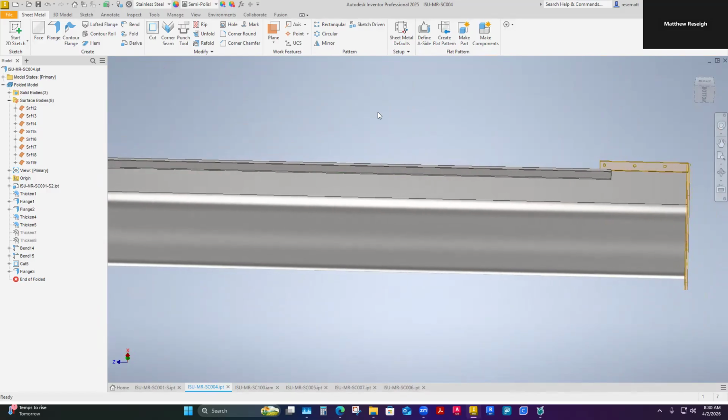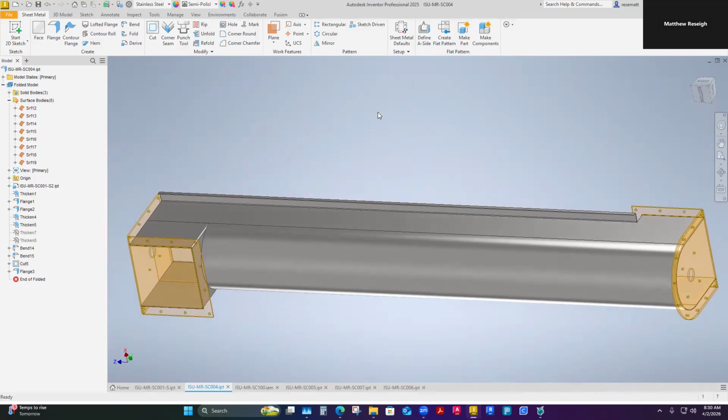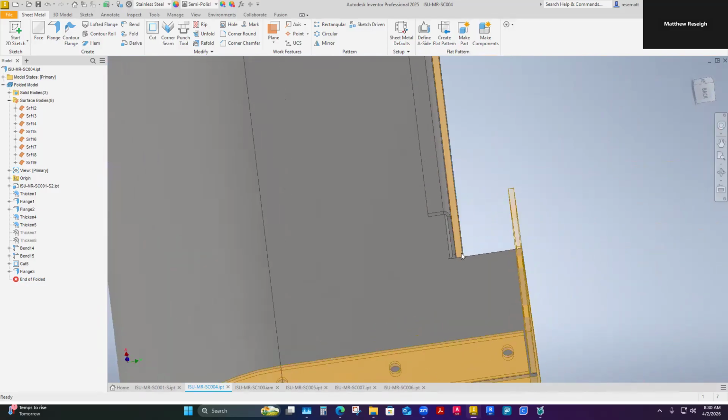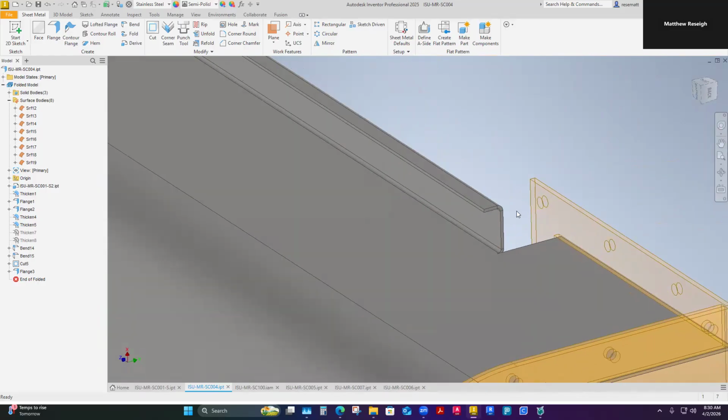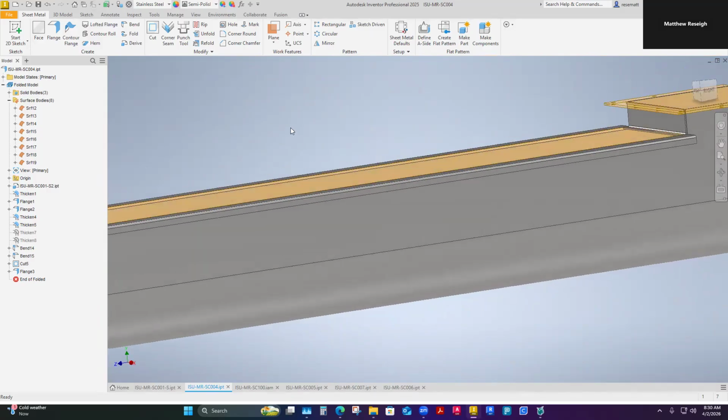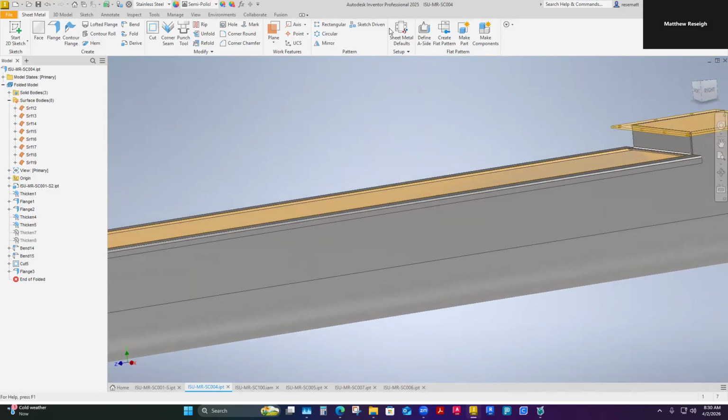And so you have to position parts in the equipment so that they bend strategically, which is very doable. On my flat pattern, probably the way you guys have it, there's just no seam there. And so this is a pretty simple fix.